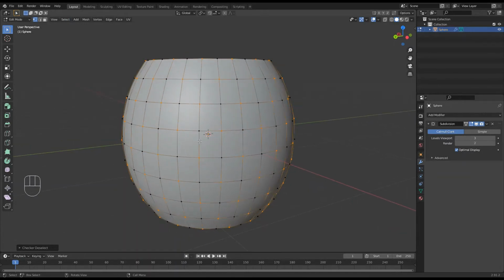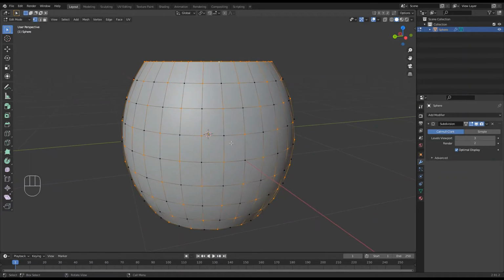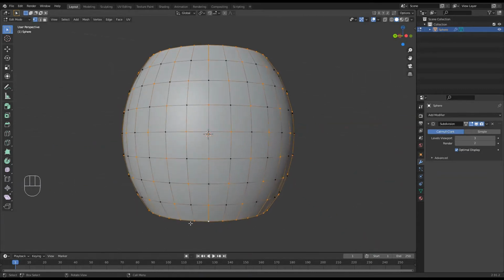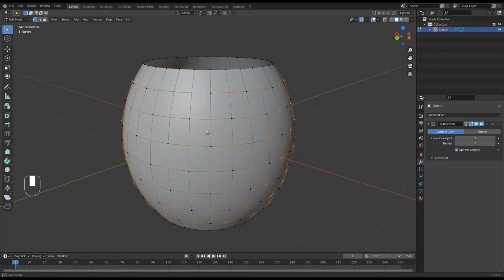So I've got every second one selected there, but I don't want to work on the top and bottom, so I'm doing this trick that I did in the cups as well. So what is it? Shift, that's a multiple selection. Alt to select the whole circle of selections. Now I actually want the black ones, not the orange ones. So Control I is invert. So we're back into business there.